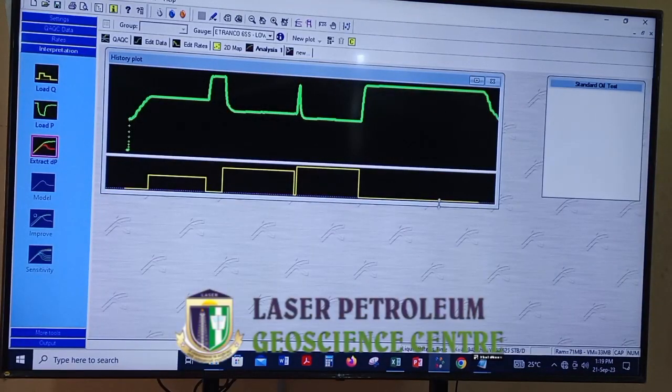I click. If you click, you should be here. Are you here? Analysis. Click on analysis. Have you clicked on analysis? Yes, ma'am. It's analysis 1 that will show by default. So the next thing you have there is your extract dp. dp is your derivative. You want to get the derivative, and it's the derivative that will help you to do interpretation. True or false?